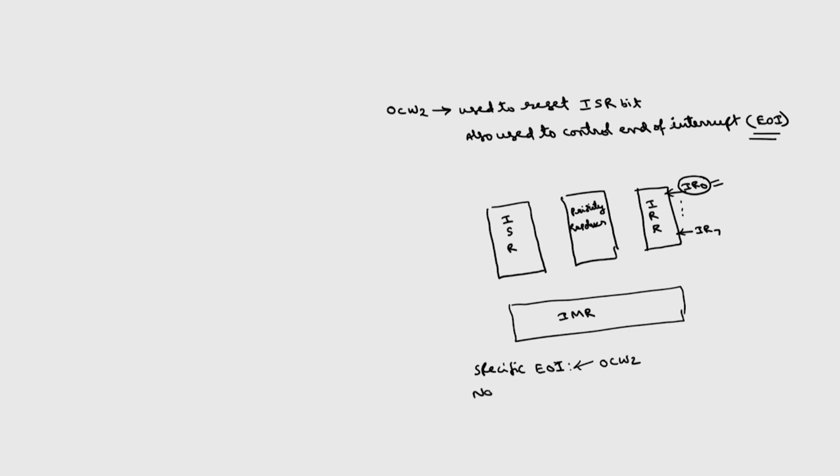Whereas in case of non-specific EOI, as the name implies, by default the interrupt which is currently being served, the highest priority interrupt, will be handled.